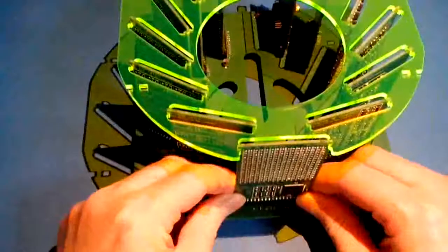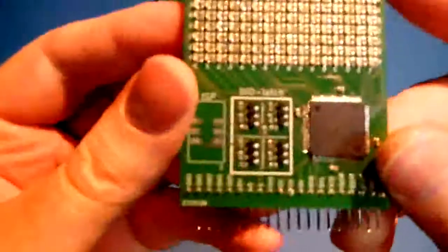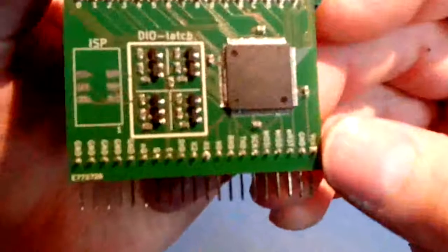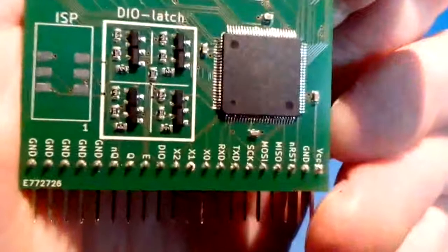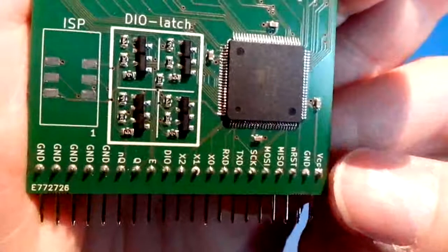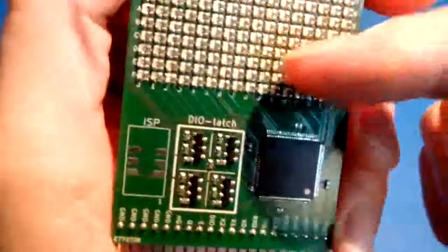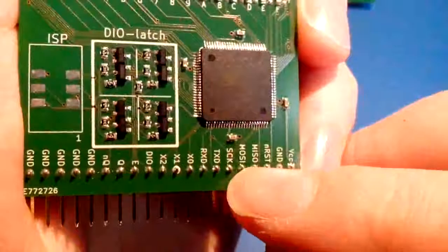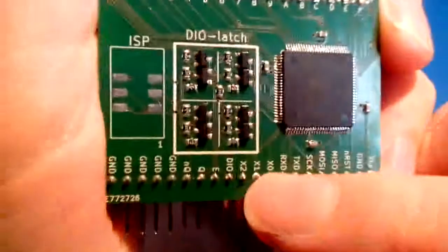I will take this actual board because that's the only one I have, to be honest. It's not very difficult to remove, as you can see. Now for inputs, it's probably pretty obvious, but not sure if you can see that now. Inputs are VCC and ground as a supply voltage. Most of the signals are the interface to this display unit. So there's SPI signals, there's UART input, these are debug signals, I think.